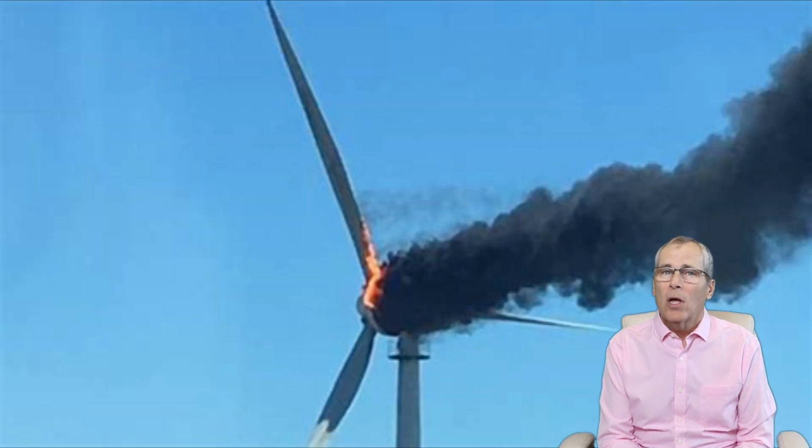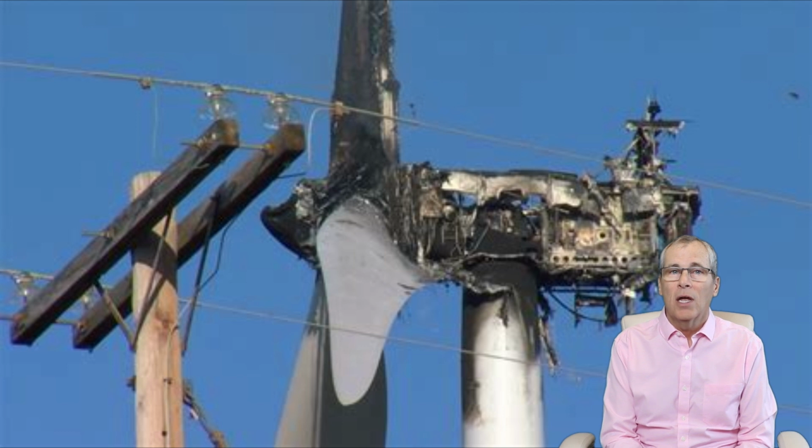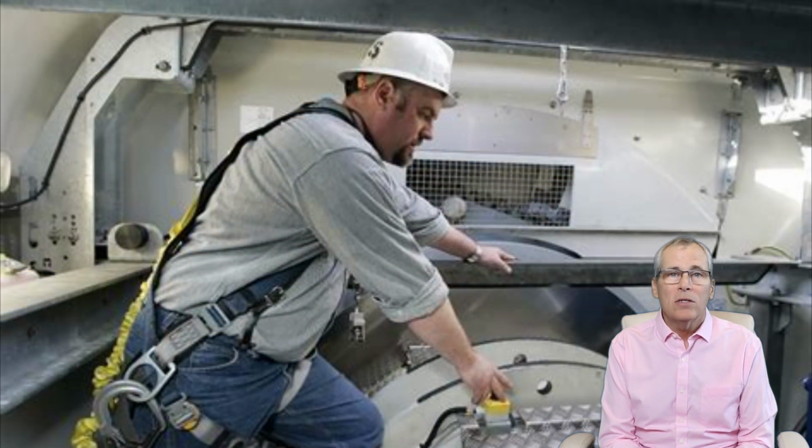In addition, it's important to have a good fire detection and suppression system in place, and regular training and drills for the personnel so that they can quickly respond in case of a fire. In summary, wind turbine fires associated with obstructed air filters due to unanticipated dust conditions can be a significant risk for wind energy operators. Regular inspections, maintenance, monitoring, and having fire detection and suppression systems in place can help to minimize this risk.